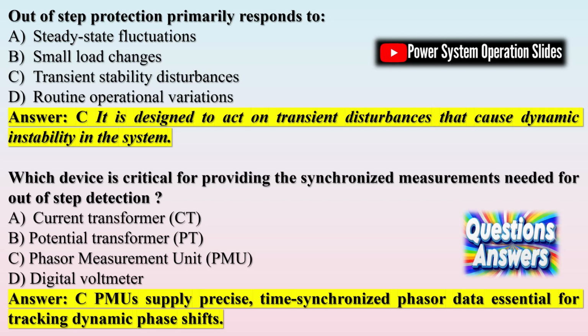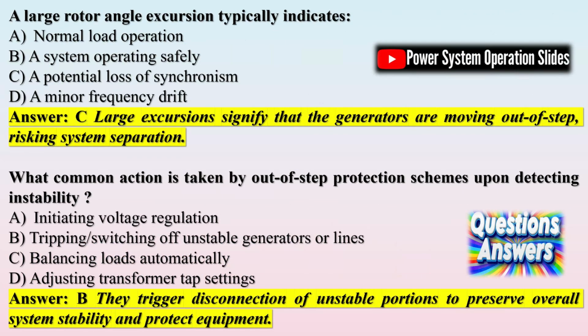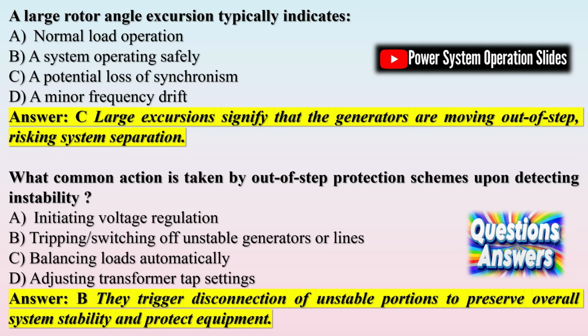In some schemes, distance relay elements are initially blocked during power swings via OSB. But if a fault is detected, characterized by abrupt changes in impedance or voltage and current parameters, the circuit unblocks the relay to clear the fault. Protection coordination: this dual-mode operation ensures that while the system benefits from power swing stability, genuine faults are not missed, thus preserving system integrity even under adverse dynamic conditions.